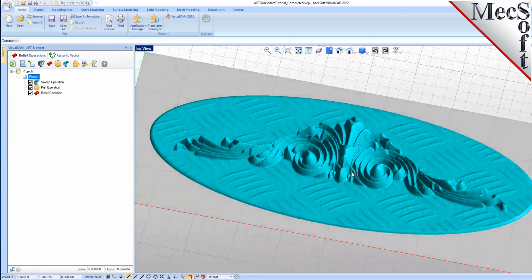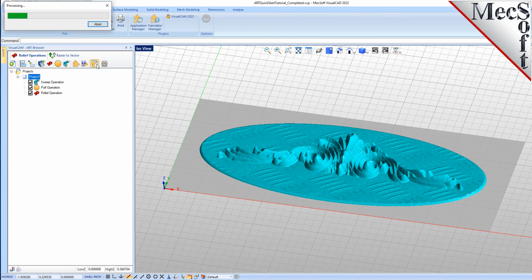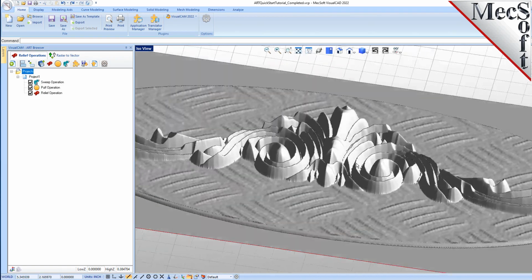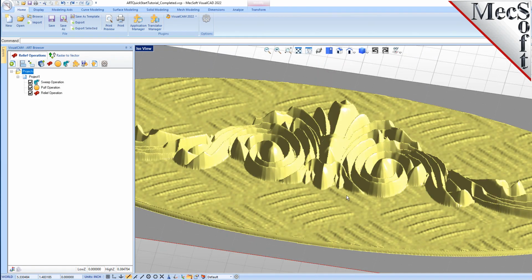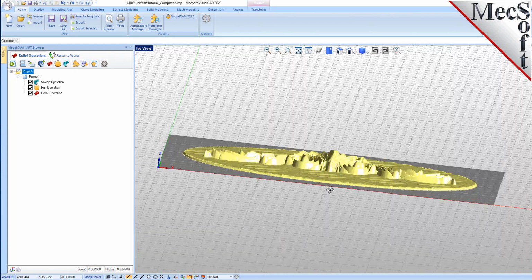Select Project 1 and then from the 3D Relief Operations tab, select Export as Meshes to CAD. Note that you must export the 3D relief operations before the geometry can be used within the CAD system. Once the export is completed, select the Projects folder at the top of the project's tree to see only the CAD mesh geometry in the graphics window.